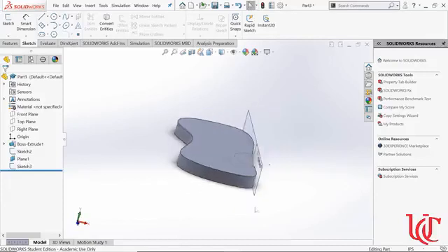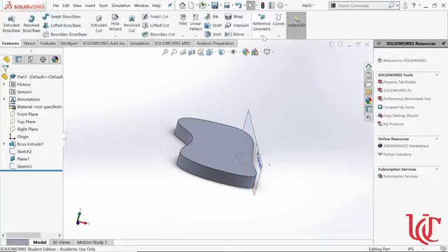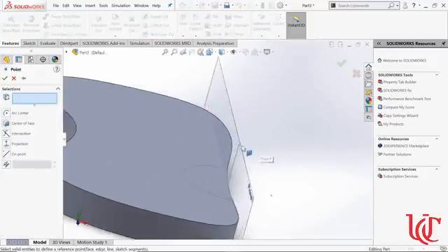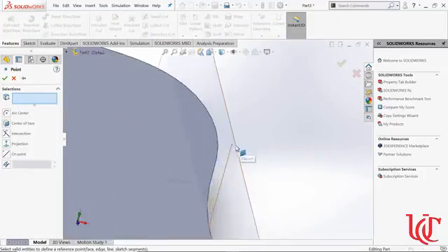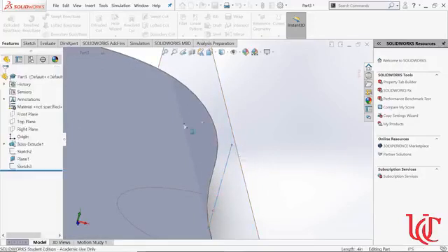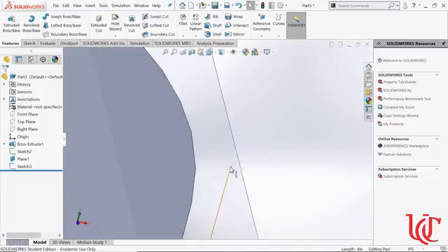And say I have this. I want to loft. I'm going to loft just to a point up here. You could loft to a totally different sketch, offset from this plane up here, to a different shape, and I'm going to loft to a point. So I'm going to say reference geometry point, so I can have an actual point to select. And I want to select the actual point.